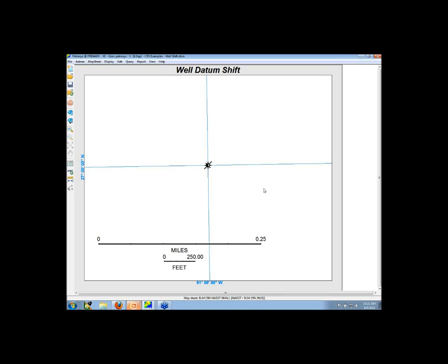And so one thing to be cognizant of is whenever you're looking at data or you're looking at your well locations or any other type of location data, if it ends up being that perfect, you might want to check it out and make sure, because sometimes this could indicate some sort of rounding problem. You know, this data moves around a lot, you can end up rounding it at some point and just cutting off the more accurate data. So a couple seconds off ends up getting moved a couple hundred feet on accident.